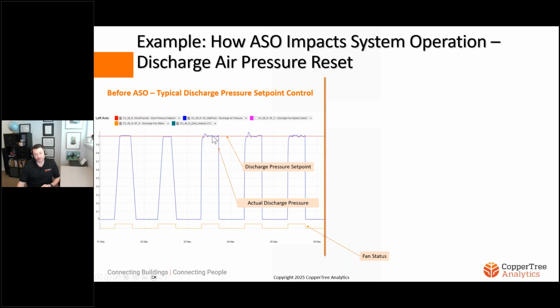And so it will achieve this pressure by modulating the variable frequency drive on the fan, right? So it'll say, okay, I need more fan speed or less fan speed. I always got to stay at 1 inch water column. And the reason why is because there's some balancing report that was either done in 1986 or last week, whenever it was done, which the test and balancer said, okay, well, based on all the balancing we've done, this is the discharge pressure set point that we need to maintain in order to assure that end of line pressure gets maintained on a design day in the middle of August, right? So while the efficiency comes from modulating the fan speed in order to maintain that 1 inch water column, the question should be, is that 1 inch water column necessary, or should we be not doing that?